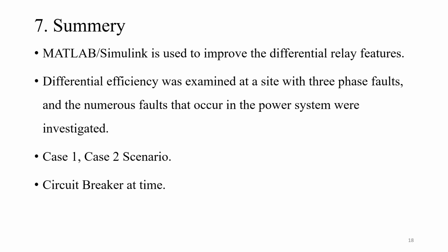As shown in case 2, if an internal fault occurs in the transformer sending side, the differential relay will send a signal to the circuit breaker at a time which I have investigated as 0.1 seconds, causing the circuit breaker to open, because the current signals of the current transformers are not identical as a result of relay operation.